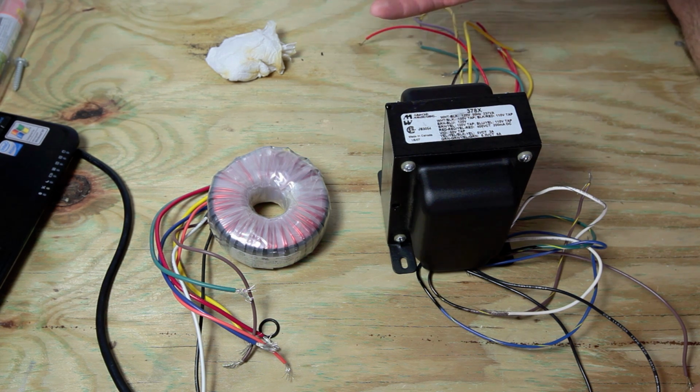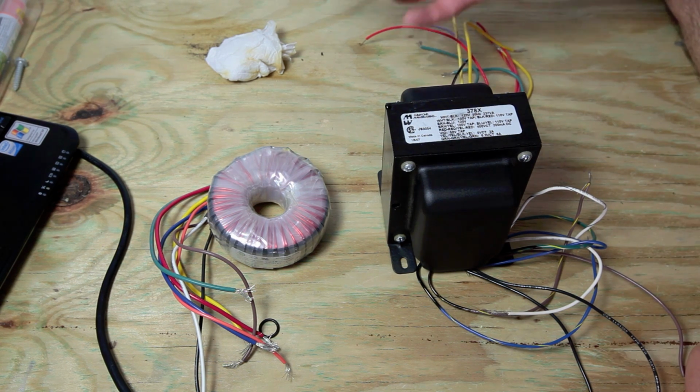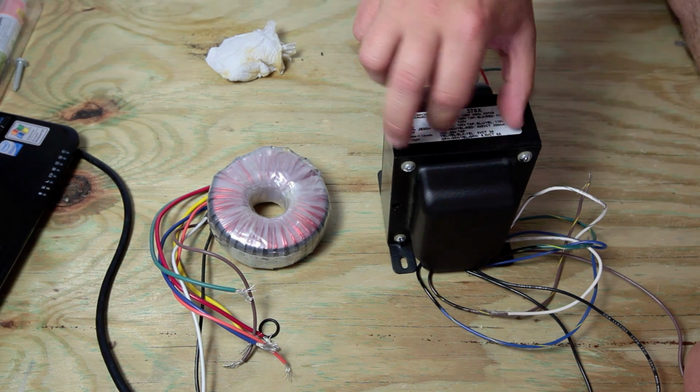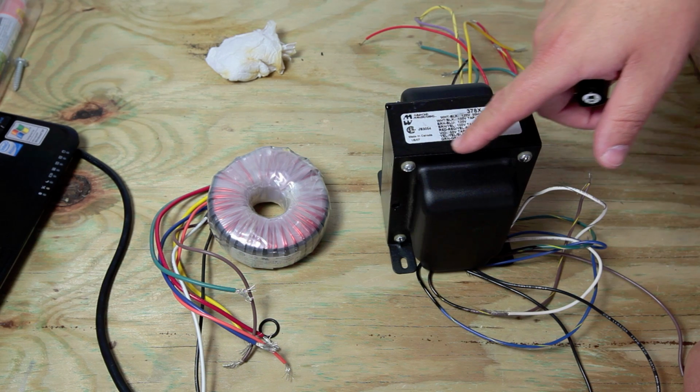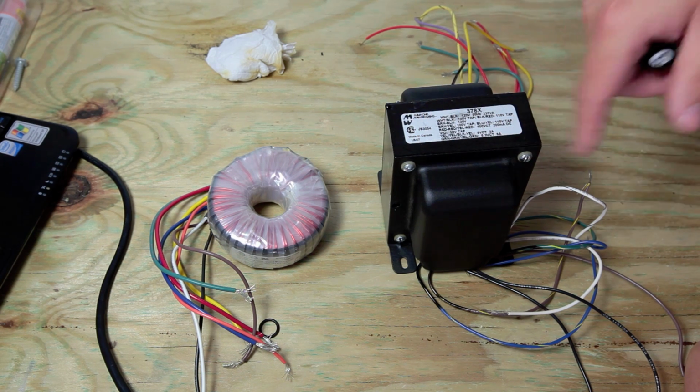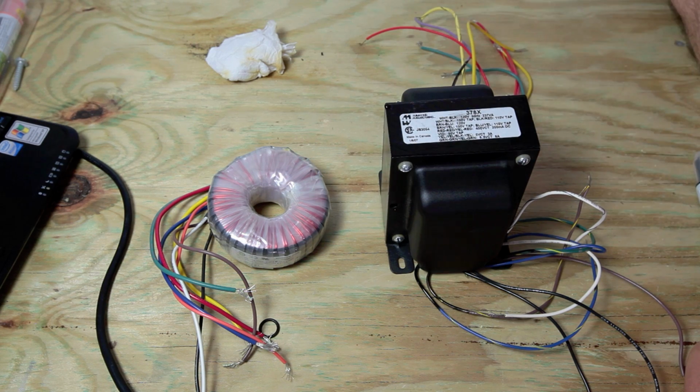In that way, they can still maintain the permeability of the core, but try to keep the eddy currents from getting around to all the layers, right? You can still get currents in the individual layers, and they're very thin. I mean, they're like 0.5 millimeter or something thick. They're pretty thin. But that's why they do that, to improve the performance of the transformer.